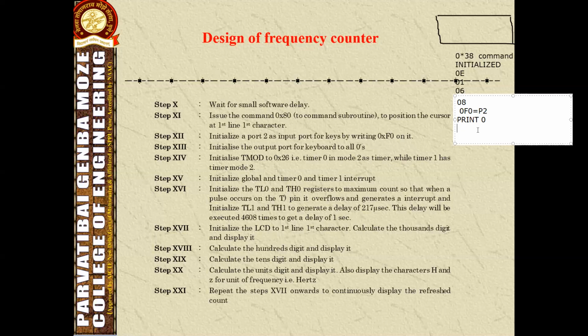So we have to set TMOD where there are two timers: T0 we set for mode 2, and timer 1 is also set for mode 2.